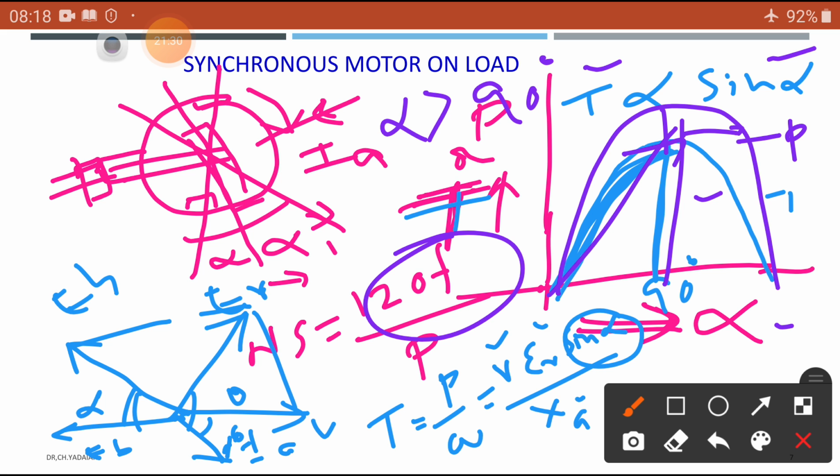What do you mean by resonance? Already you have seen it in physics. The amplitude of these oscillations of the rotor at its magnetic axis builds up to a large value and may eventually become so great as to throw the machine out of synchronism. Then the motor will stop, as the motor and stator coupling goes out of synchronism.